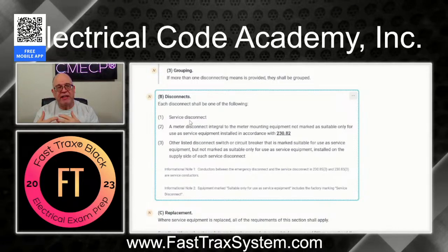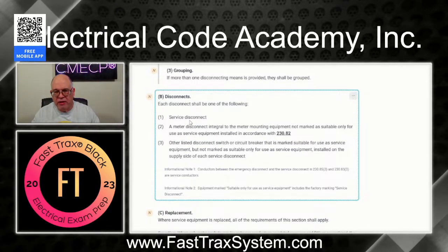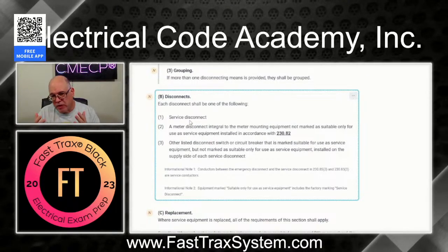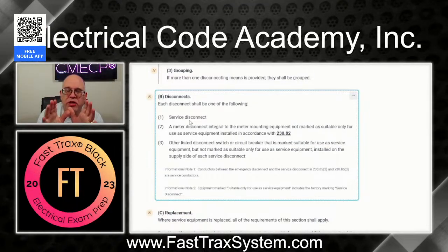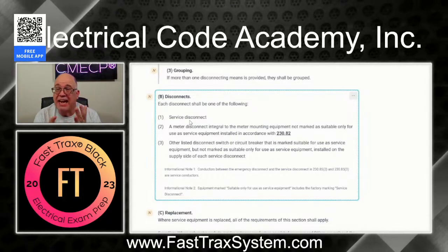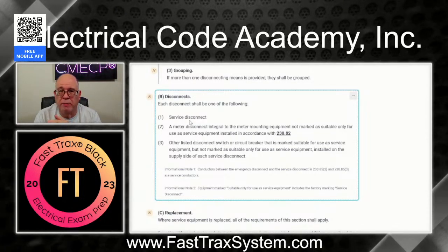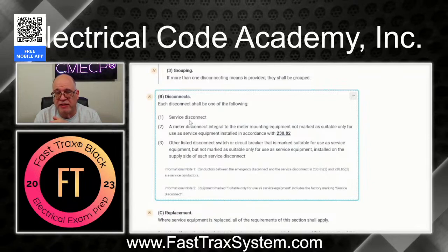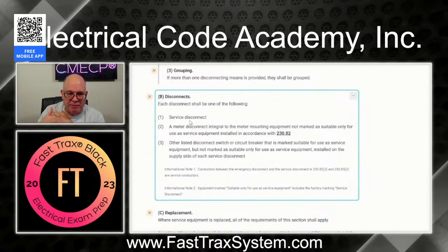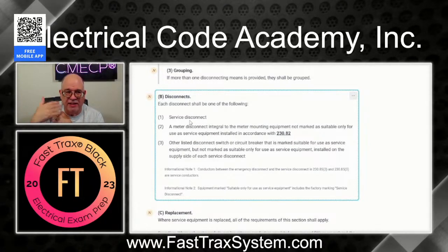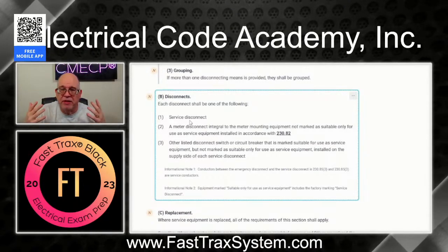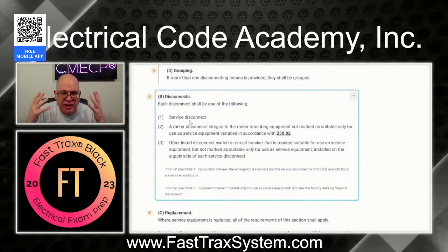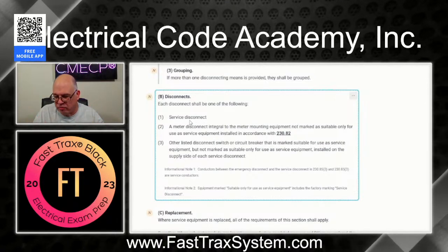And then everything after it, you have all your breakers, and then you'll have your branch circuits coming out of it. So that could be your service disconnect, your service equipment, and your emergency disconnect. And he'll show you what you've got to do to label it in a minute. Now, that's probably what people do with the NEMA 3R exterior panelboard type of application, right?